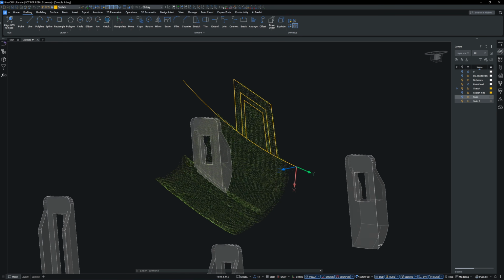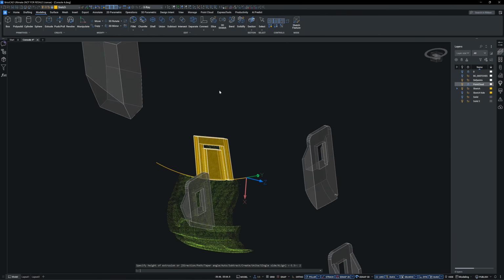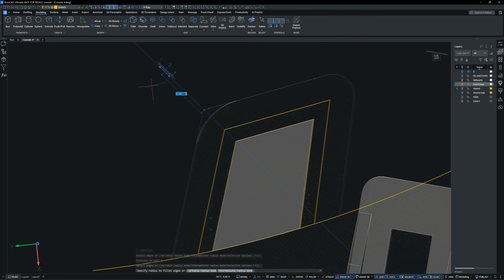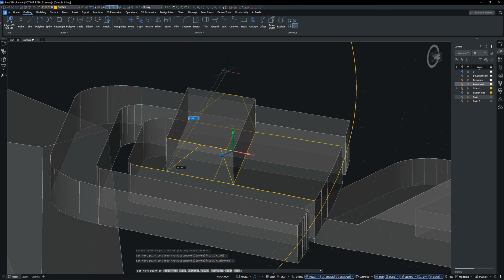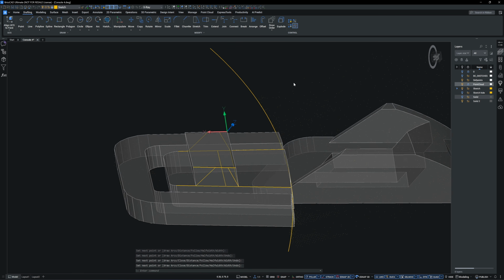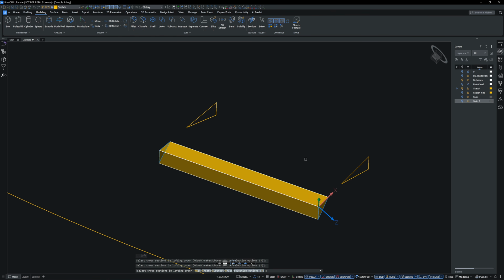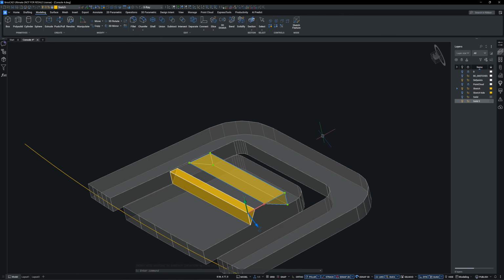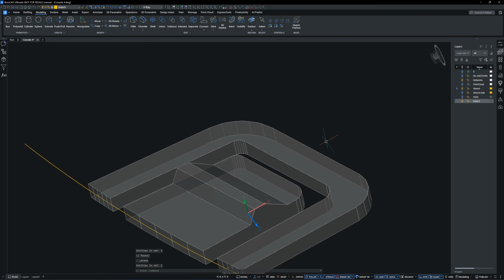On the side wall, there is a thin clip that isn't rectangular. Creating the lock key is a bit tricky, and it has to be formed by lofting. This clip extends beyond the flat sidewall surface that I plan to place on the build plate, so it may need to be printed separately.